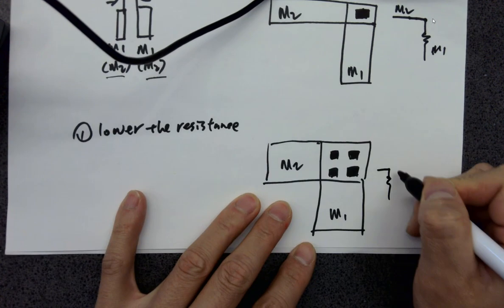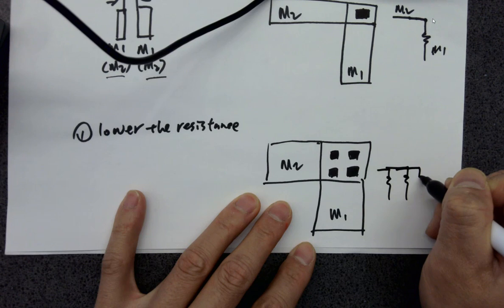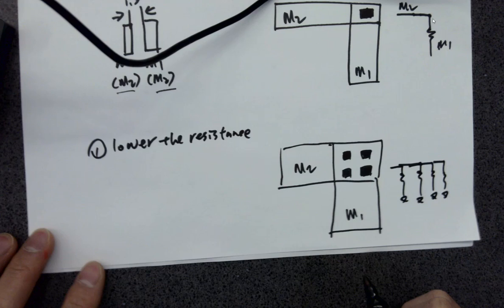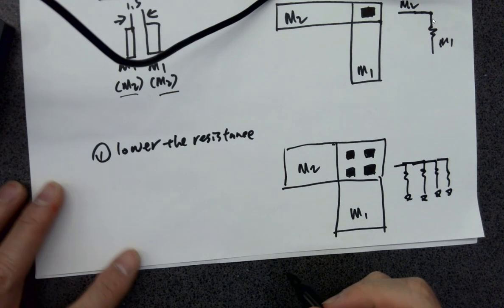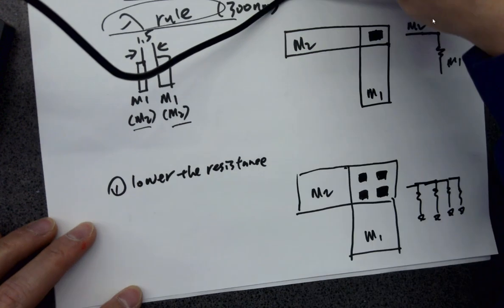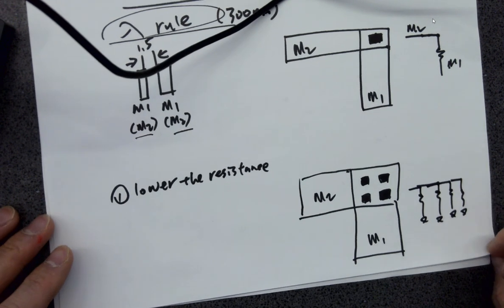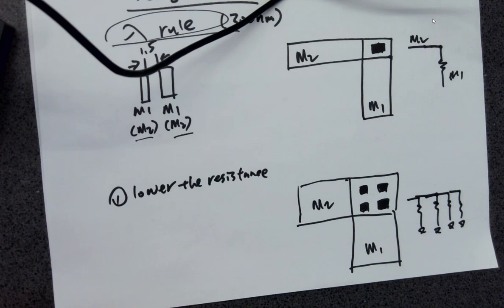So you got 4 in parallel, so it can reduce the resistance, which is important because a lot of times in the nanoscale there will be a lot of really thin wires routed for a long distance, so it's going to introduce a lot of resistance. The chip doesn't have a big area, but the wires are super thin, so that's why the resistance will be pretty significant. So it's introducing time delays.